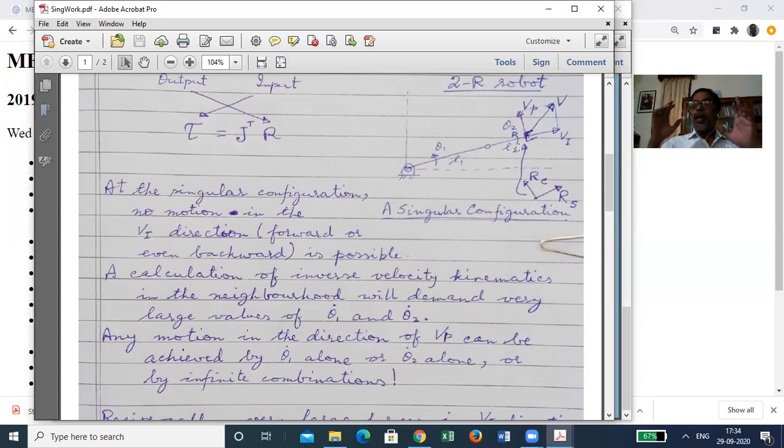So, I mean, if he pushes too hard, then your joint can break, but that is not what you are budgeting for. You are budgeting for your actuator failing, okay, because joints can take enormous amount of forces. And rigid body, your elbow, your arm is almost part made of two rigid links, okay. So you are budgeting against your actuators, the muscles at the joints. So in order to lessen or reduce the load on the actuators, you put your arm straight and stop the adversary in this manner. Okay. So at similar configurations, at some directions, some degrees of freedom are lost. Some velocities, some motions are not possible, and in that direction, the force carrying capacity gets amplified enormously.